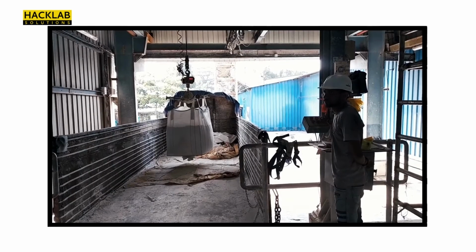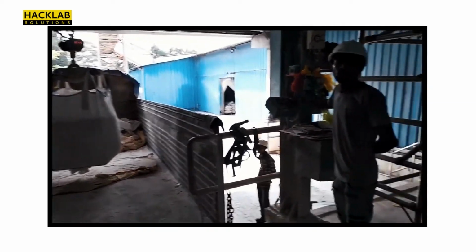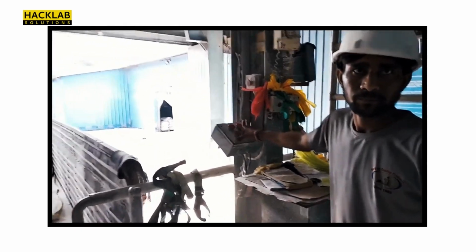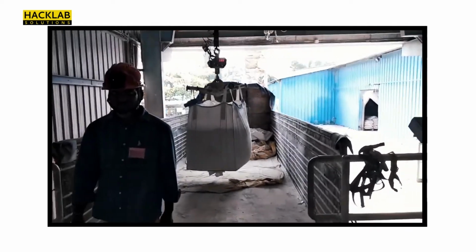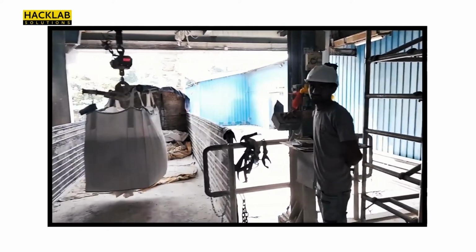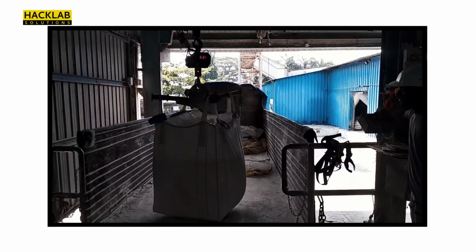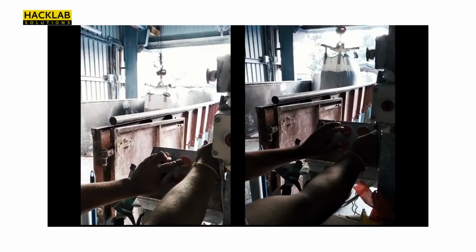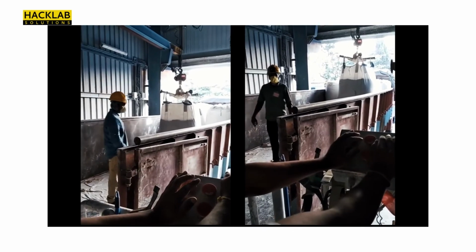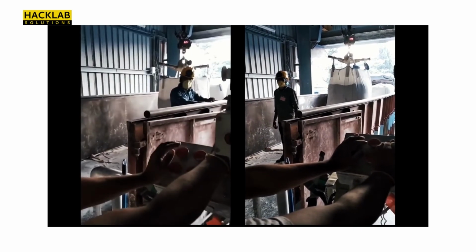Step 4 is execution. In this process we execute the above analysis with the help of our solutions. As you can see here, the loaded crane hook doesn't move when the worker is standing near to an EOT crane even though the driver is pressing the button for moving. But as soon as he crosses the emergency range away from the danger zone, the machine starts moving again. When the worker stands near the load again, the machine again stops.